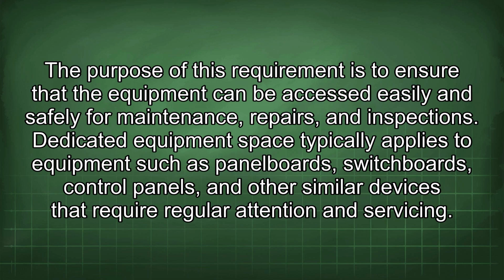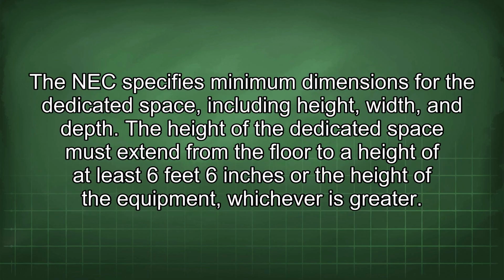and inspections. Dedicated equipment space typically applies to equipment such as panel boards, switchboards, control panels, and other similar devices that require regular attention and servicing. The NEC specifies minimum dimensions for the dedicated space, including height, width, and depth.